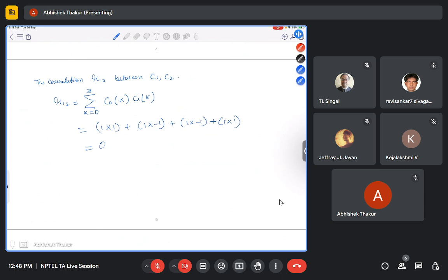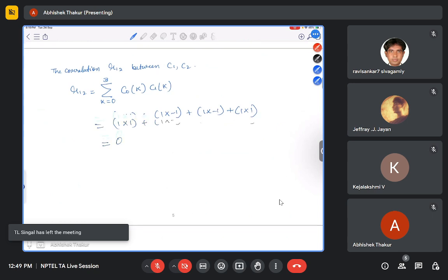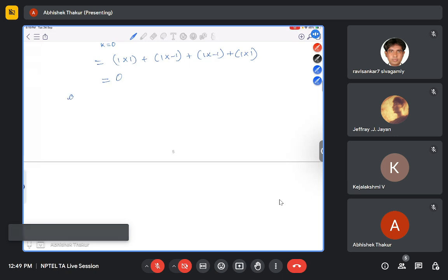This helps us recover the symbols of the different users from the composite signal. This is one of the key properties of the codes employed in the CDMA wireless system. So the codes are orthogonal to each other.